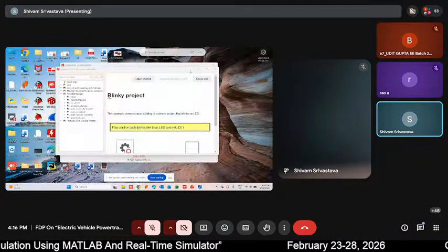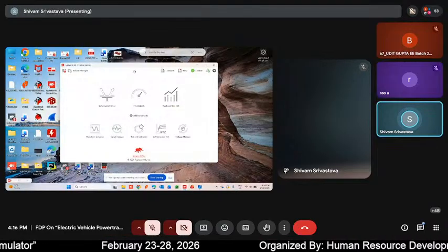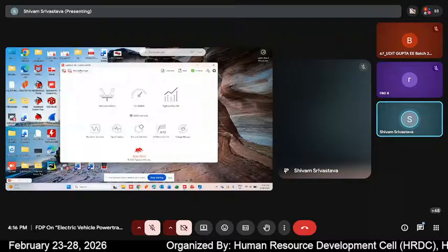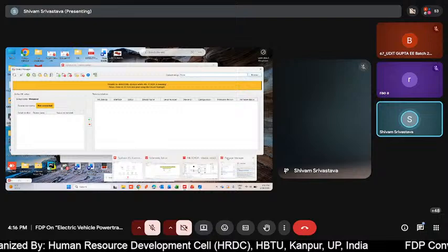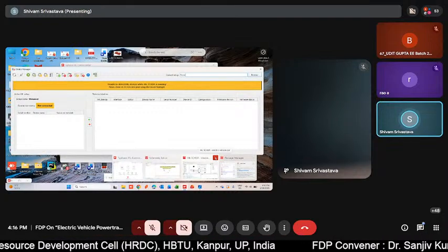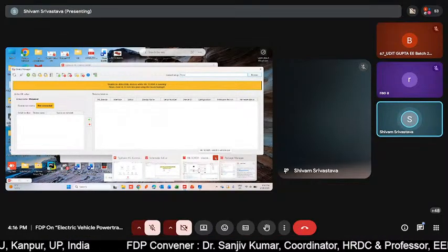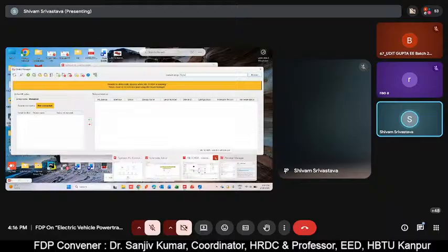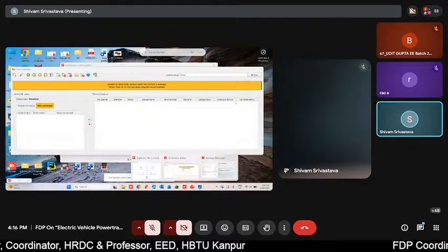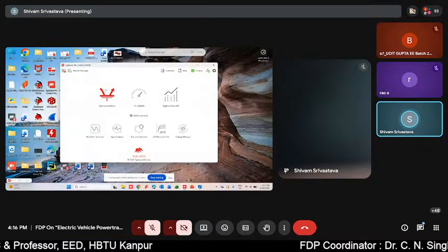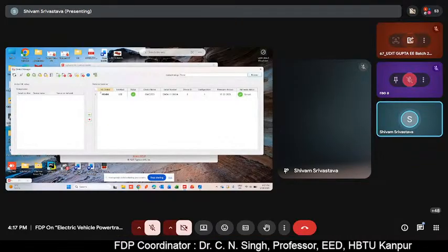So you already know that the LED has double blinked on the front panel of the HIL device. You can see that my SCADA is already running. It is a good point to remember that whenever you use this HIL device, the device manager will only detect whether the HIL device is active once the HIL SCADA is off. So I can close the HIL SCADA and again check whether my HIL device is available to me or not.